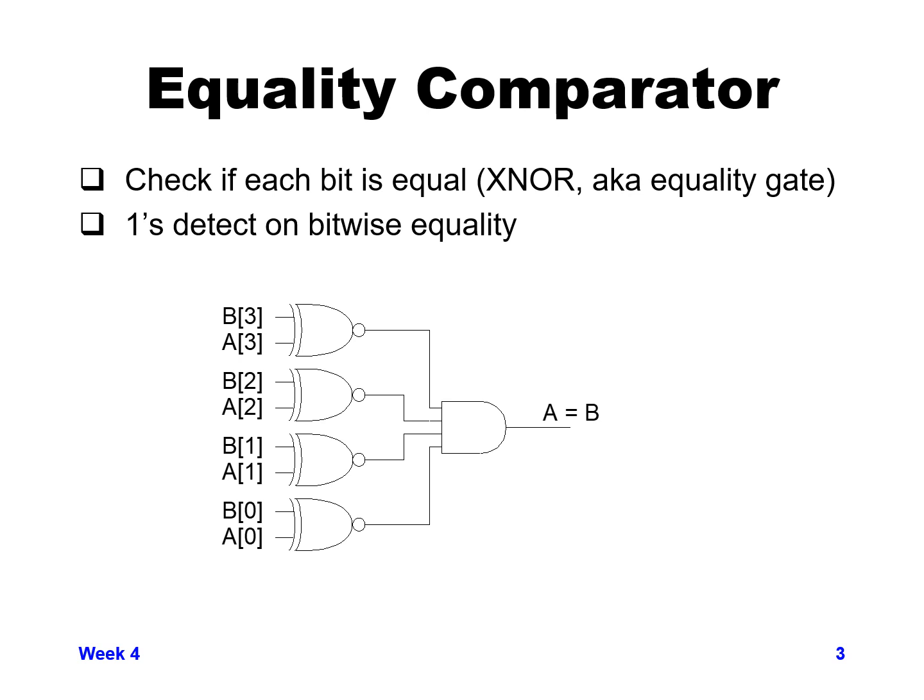So in an XNOR, if both bits are 1 or both bits are 0, we get a 1 out. So it's inverted from an XOR. Basically, if both bits are equal, we get a 1 out of an XNOR gate. So both bits are 0, or both bits are 1, we get a 1 out.